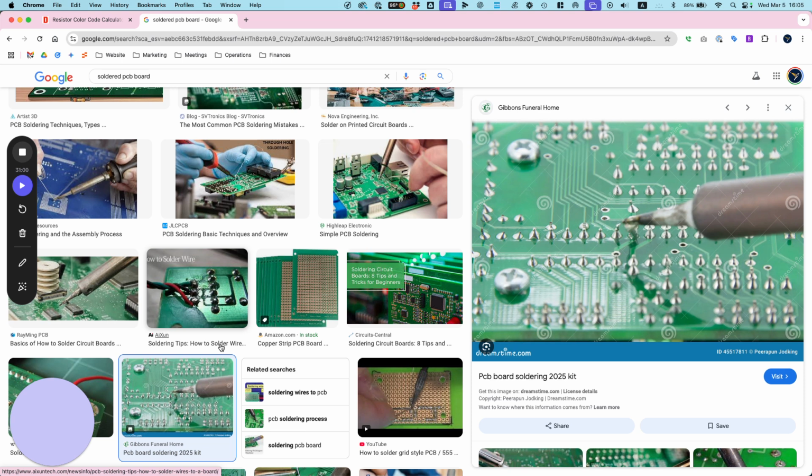What is it going to be? 14.8. That's right. But what's the difference? You still get 14.8, but because they're in parallel, you'll have twice the current. So why would they do something like that? What's the difference between doing a 4S like this, just this, and then having a 4S2P like that? Why would you do one over the other? More energy.